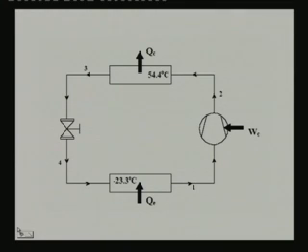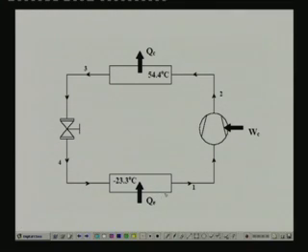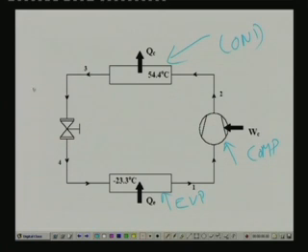That means you have the 4 basic components. Since it is a standard cycle, you have the evaporator, compressor, this is the condenser, and this, as you know, is the expansion device. And this temperature is specified, evaporator temperature minus 23.3 degrees centigrade, and this temperature, condensing temperature, is specified 54.4 degrees centigrade, and it is a saturated cycle.